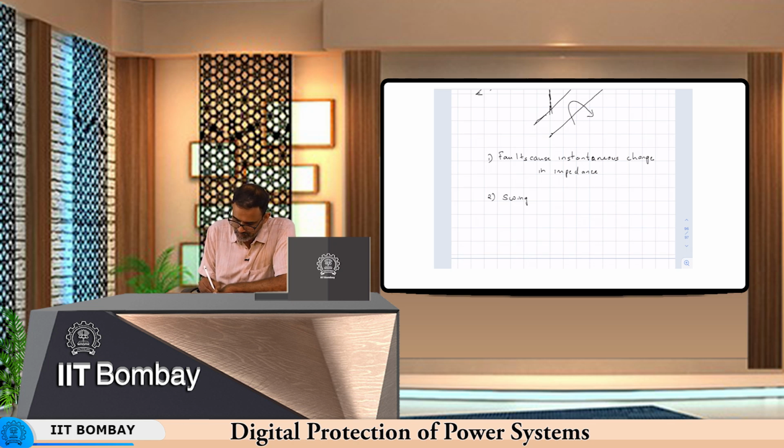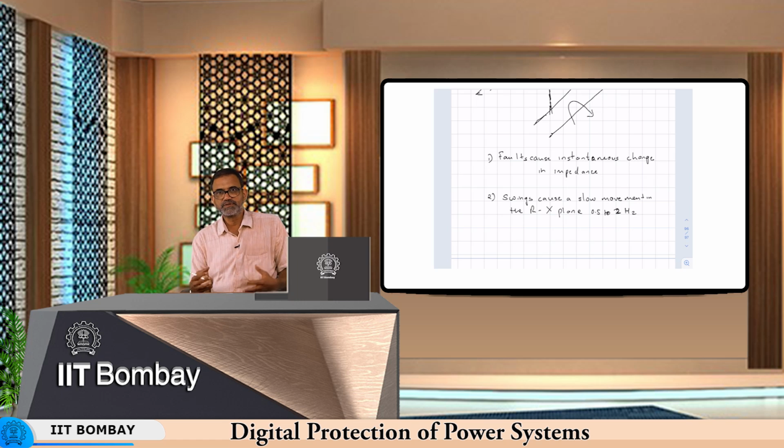Swings, on the other hand, cause or result in a slow movement in the Rx plane. They are of very low frequency, in the range of 0.5 to 2 hertz. Why is this? Because there you have synchronous machines, you have machine inertias, and to change the rotor angles it takes time. So, the power swings will cause a slow movement.